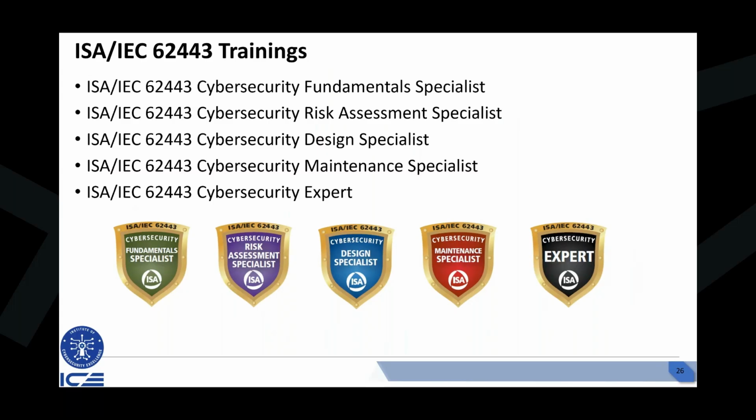So there is no segregation required between L1 and L2. And I'm guessing you mean, again, from Purdue model perspective. The answer is there is no such requirement to have any kind of segregation between any levels, because the levels are not cybersecurity levels. You may have to have segregation between two L1 devices, for instance. You may need to segregate two controllers.